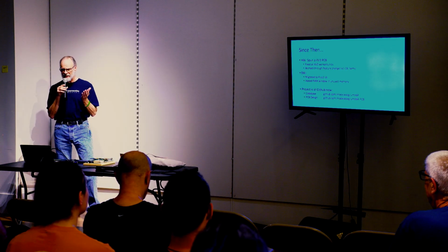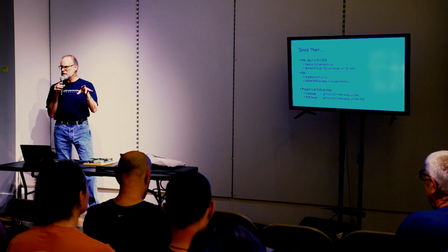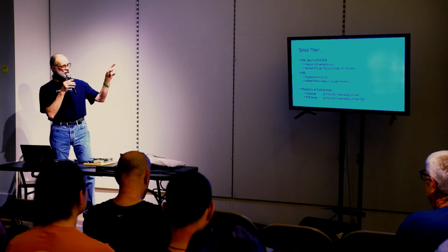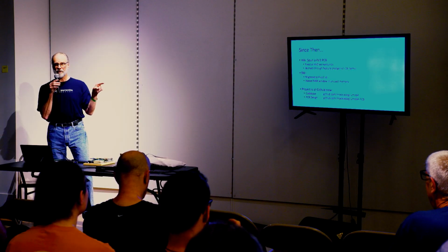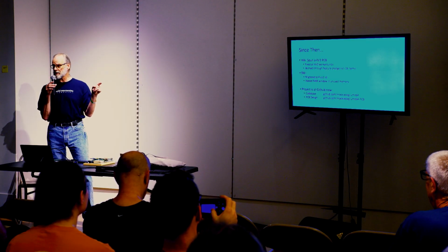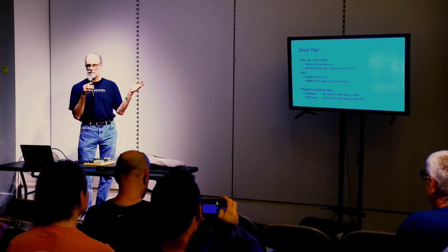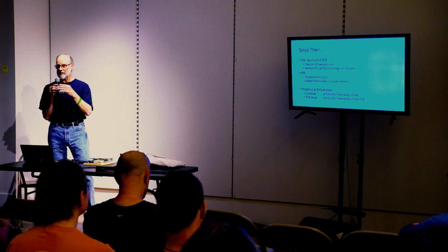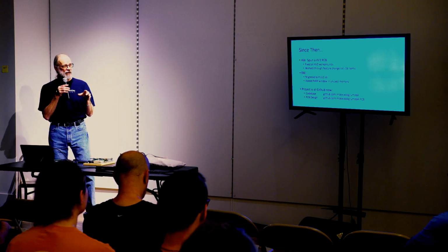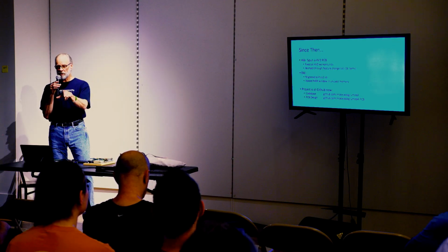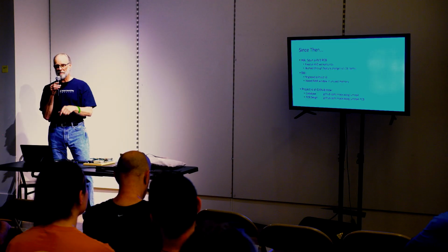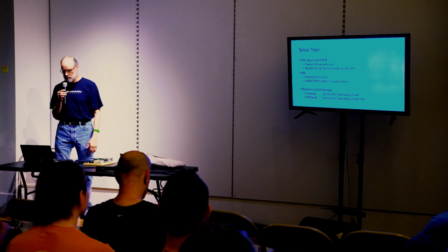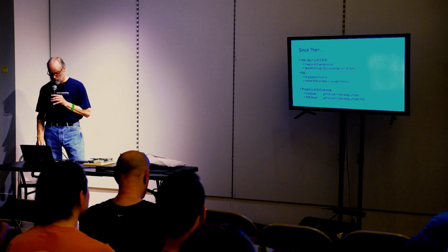Someone asked me last night, how come I used a plug-in module for the processor? And the answer was exactly this. I did not know that there was going to be a Pico 2 when I started this, but Raspberry Pi helpfully came out with the Pico 2, which runs even faster, has twice as much SRAM, and all I needed to do was unplug the old Pico, plug in a Pico 2, and in about 5 minutes of software, I had an upgrade. So that's why I like plug-in modules.